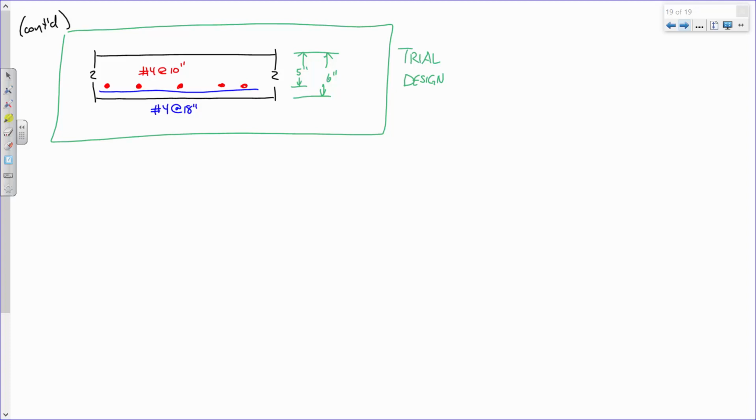Does that make sense? So that would sort of be my best answer: for us, whenever they're equal, go with the fewer bars, but otherwise go with the one with the minimum area. But when you get out of here, use some common sense, looking at your labor rates and material prices, and see what's actually going to result in the least cost for the project. That's a good question.